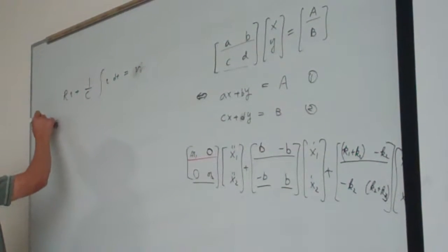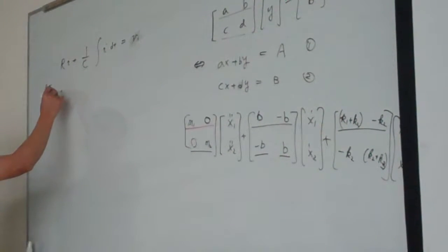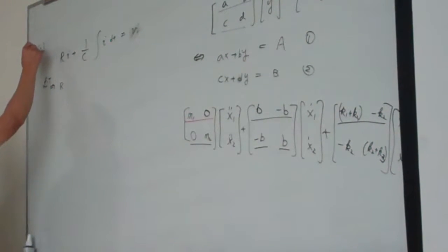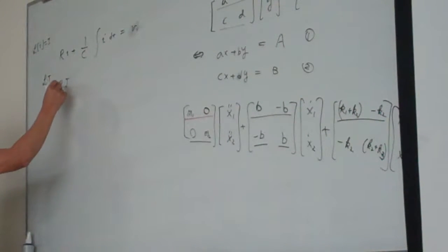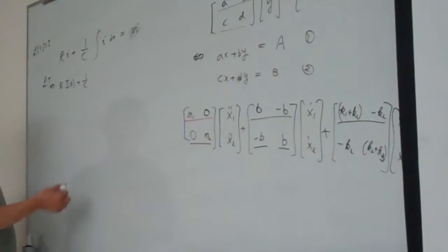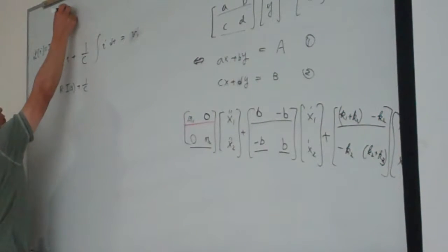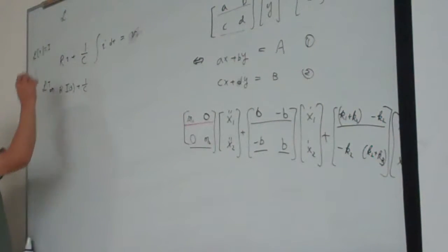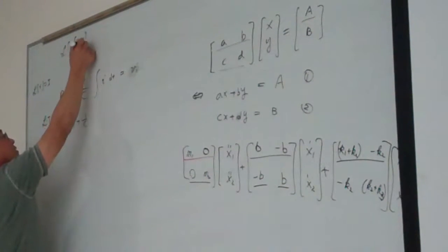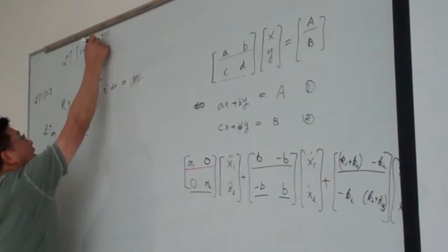From here, if we take the Laplace transform, we can get this. R is a constant, and let me define the Laplace of i as capital I, so there's a capital I of s. 1 over C is a constant coefficient. Then, if you remember the Laplace transform, the integration of a time signal is equal to that signal divided by s.